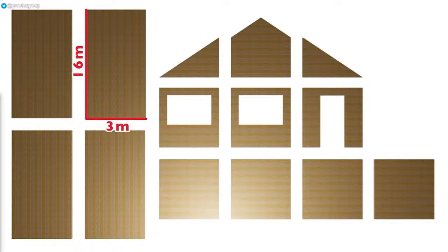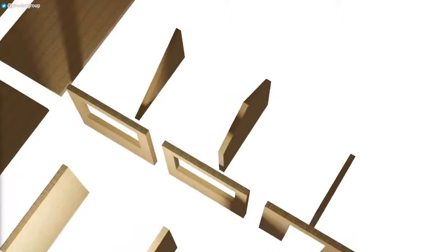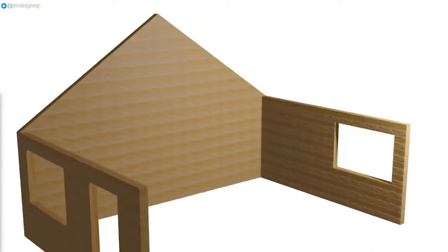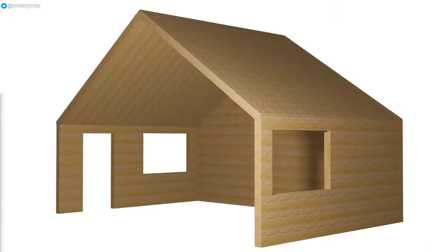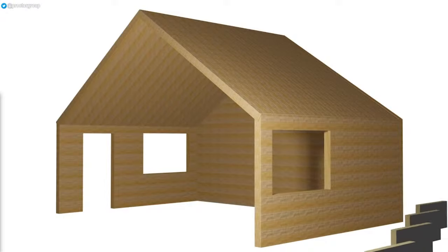The alternating timber layers give the panels excellent structural properties, and being solid, joints can be made at any point. Openings for doors and windows can be placed anywhere in the panels, but along with the general layout and structural design of the building, this must be fixed at the point of manufacture and cannot be changed later. Once the panels are manufactured and delivered, the on-site erection process proceeds extremely quickly. However, should any changes or alterations be required at this stage, the delays and cost increases can be considerable.